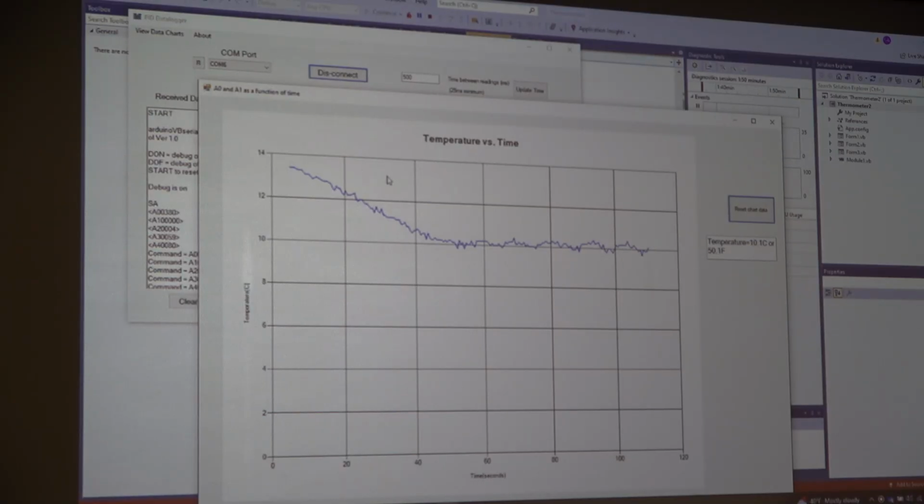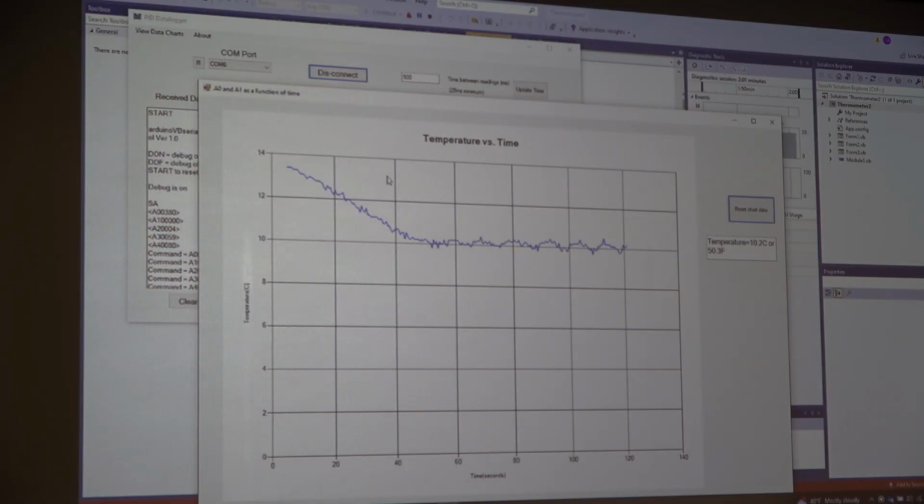So Kp, that's your initial rate of descent. That's your initial throttle. I, you've got to be careful. If you put on too much built-in throttle as you're going to set point, you're going to overshoot. You're going to ring. Okay, D. Derivative.